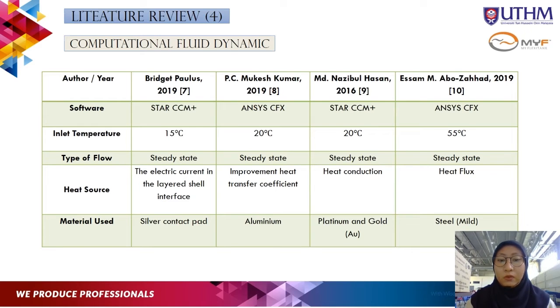Third, they used STAR-CCM+, with heat conduction for the heat source and platinum and gold as the material. And the last, they used ANSYS CFX, the inlet temperature is 55 degrees Celsius, the heat source is heat flux, and the material is steel.